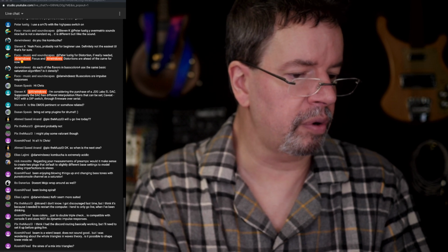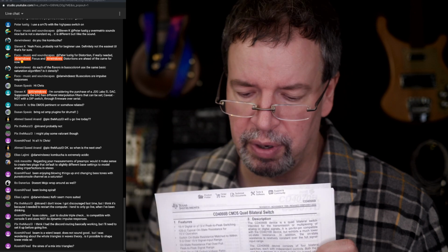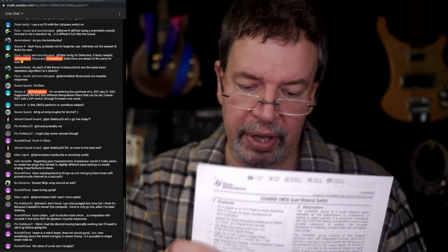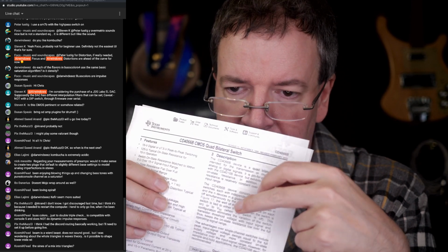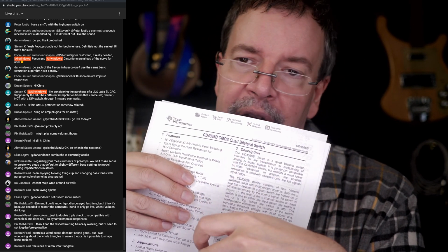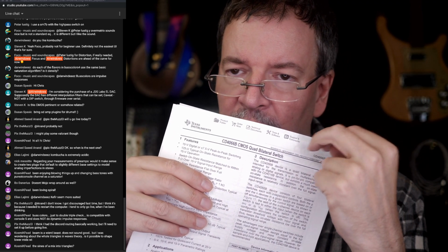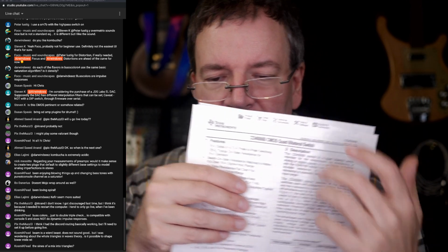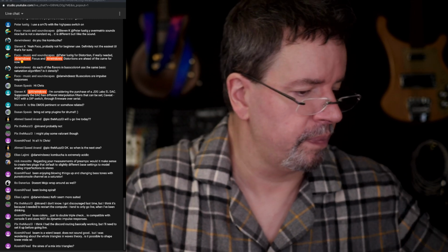You got a 4066. It's a quad bilateral switch. I got stuff like that recently as well. And the idea with the quad bilateral switch is, here's a connection, and if you put voltage into this other pin, it connects. The switch goes on. If you don't have voltage to it, the switch goes off. And it's a way of manipulating other stuff that's happening.